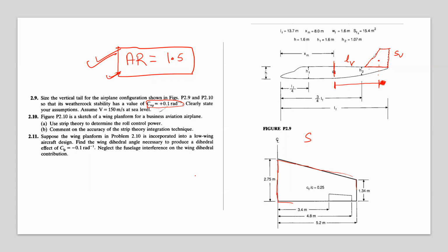Okay, a smaller wing. So a vertical tail is a wing which is vertically mounted. Horizontal tail is also a wing horizontally mounted. Okay, so an aspect ratio for the wings of the aircraft is taken approximately 10. Like 10 is a good number. It's a large number. It's fairly good.